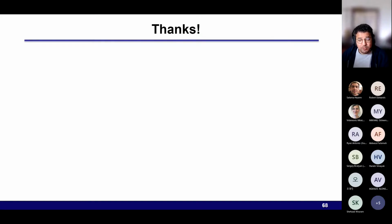I did that work 2 years ago, but the issue is that you can't decouple, so you have to do like 16 or 4 combinations of this. Basically, you have to extract the design using Calibre and then Magic, and then simulate them with closed tools, let's say HSpice or Spectre, and then go back and do the extraction with Calibre. I mean, you have the extraction with Calibre and Magic, and then run it with ngSpice. I've only done completely closed tools and completely open source, and the results are kind of different.